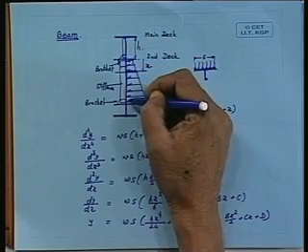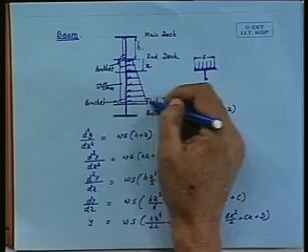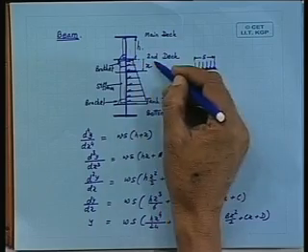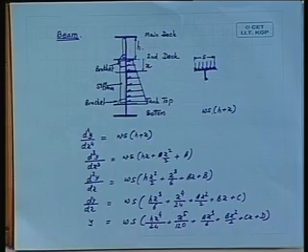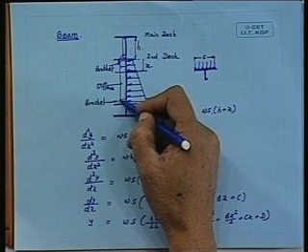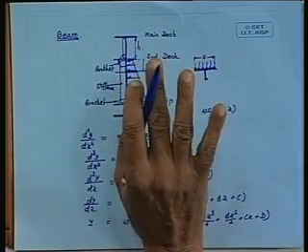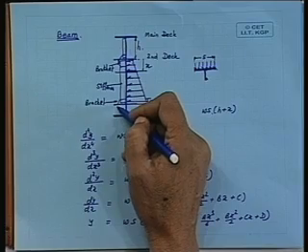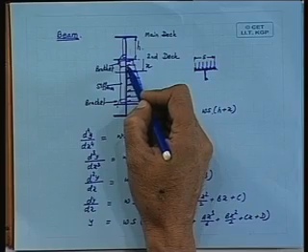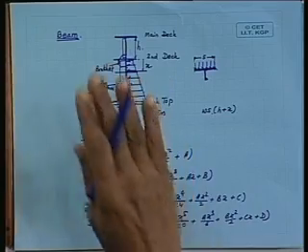Now, we have a stiffener here, we have a bulkhead plate here. This bulkhead is welded to the tank top. This bulkhead is again welded to the second deck here, which is a line contact. And then we have tried to connect the lower foot of this particular stiffener with the help of a bracket. This bracket can be a simple bracket, it can be a flanged bracket to the bottom plate here or the tank top, and here again to the top of the second deck or the underneath of the second deck by bracket. Now, they will try to provide some sort of a rigid connection,